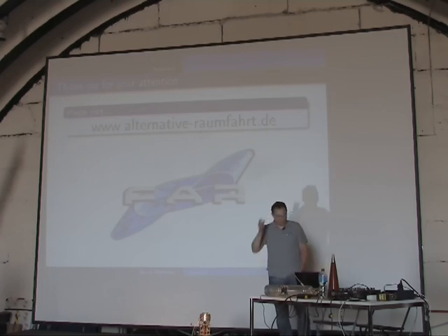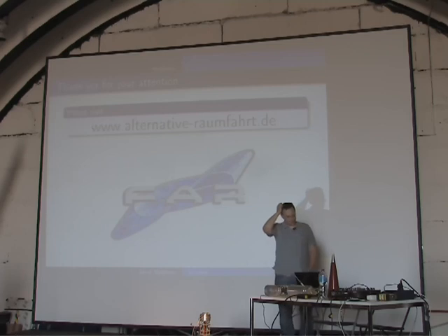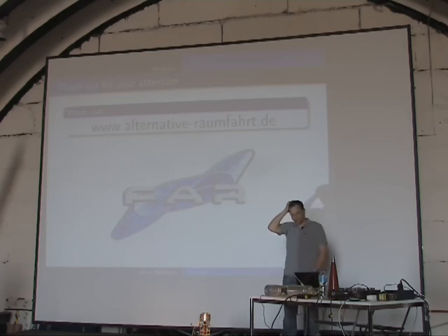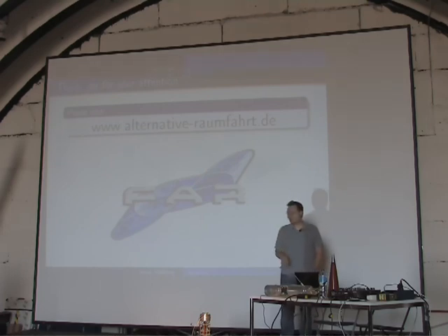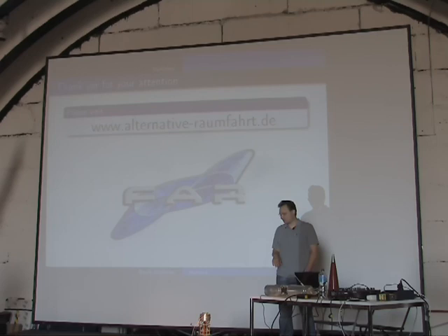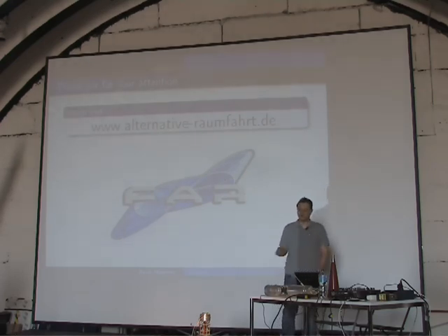Let's say one Propeller at full speed uses about 100 milliamps at 3.3 volts, so 0.33 watt per processor. And the ADCs, not to mention, have very, very low power consumption because they are slow too. And the SD card uses a little bit. So in total, I think the whole avionics uses less than 1 ampere, less than 3 watts.